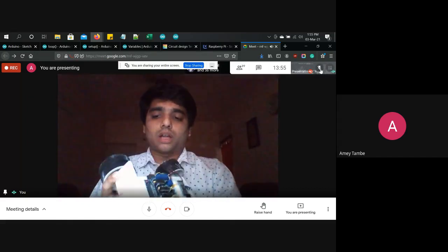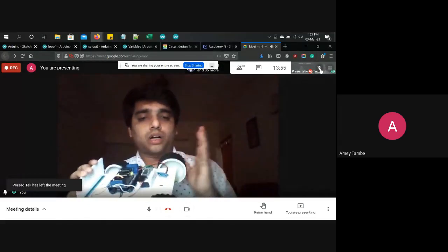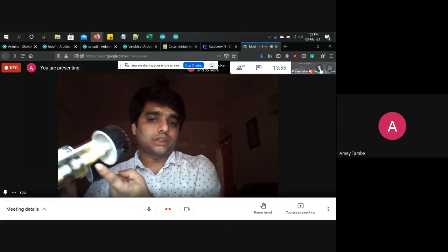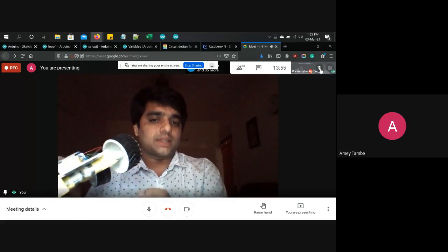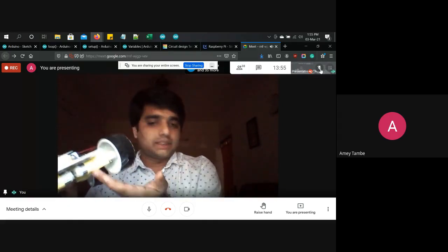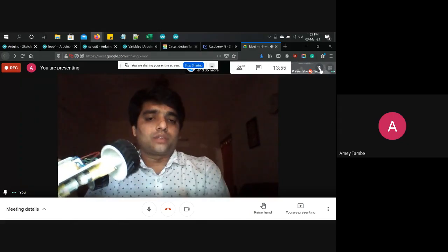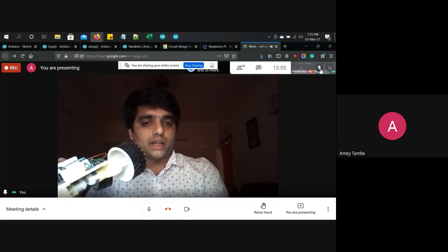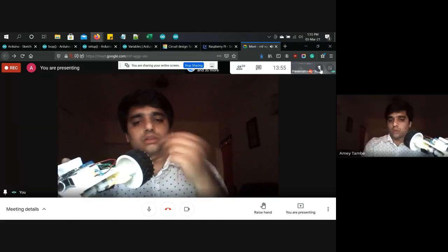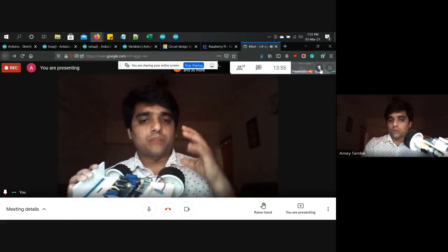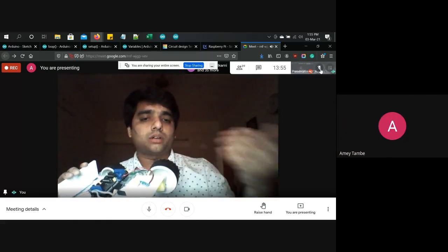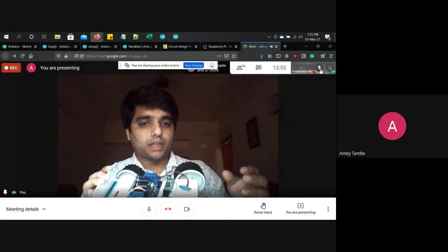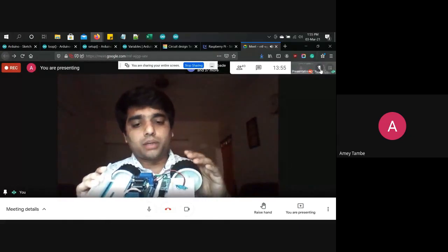Now to control the movement of our rover, we need to use motor drivers, because these motors are direct connection motors, DC or BO motors. These are the BO motors. It needs a battery to operate. If these are DC motors, direct current motors, which are the metallic motors, then it has to be provided direct power. All motors will require direct power. So the power consumption, braking, movement, right to left, left to right, all these movements, whatever we are doing through our mobile application, that needs to be controlled. So that will be controlled via a motor driver.